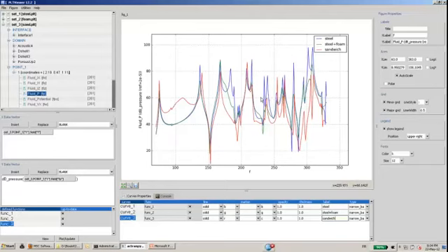But at higher frequencies, let's say starting from 270 Hertz, I clearly have a strong decrease of noise, a strong attenuation, thanks to the addition of the septum. So it's really the addition of the septum that makes the dissipation occur much more in the porous layer.